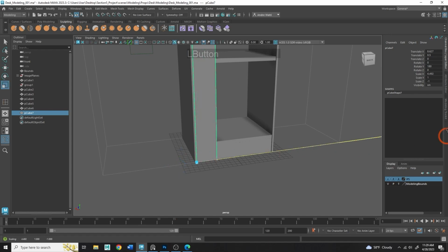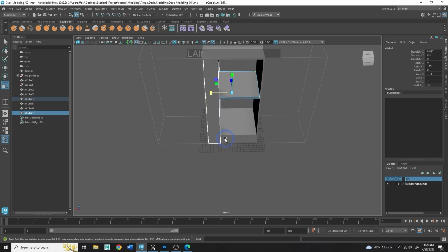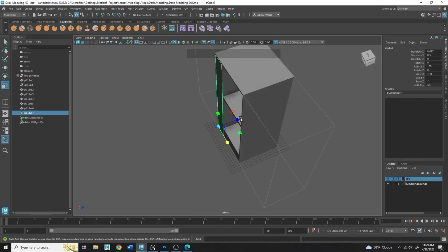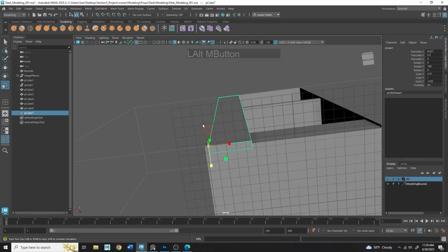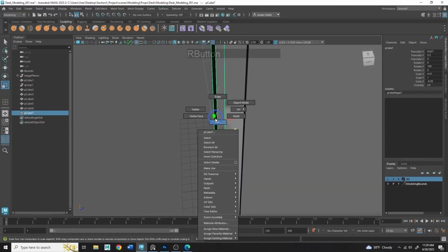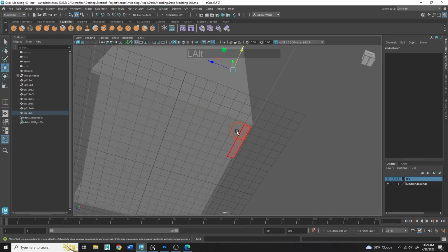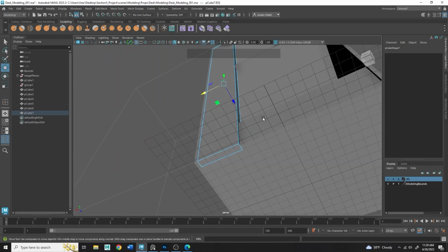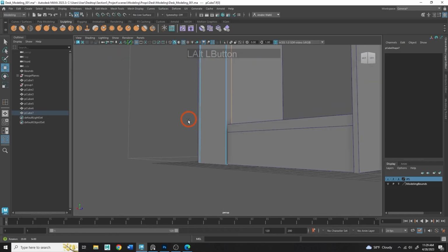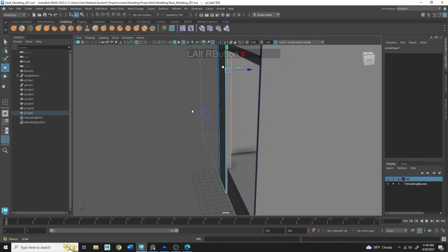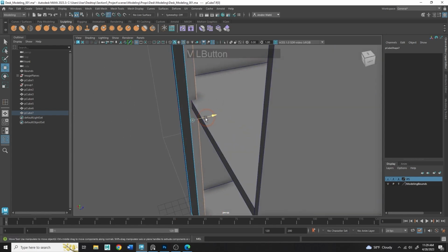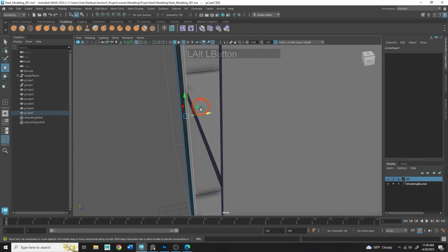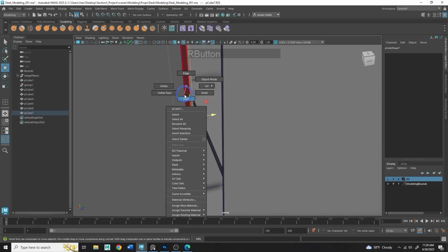From there, we can scale this across if we wanted to, or perhaps more appropriately scale it down to begin with, and start snapping these into the correct locations. What do I mean by that? Well, this face can snap to these vertices to have a tighter look. So this bottom vertice here, if I turn on wire on shaded, we can get a better feel for it. So just these outside ones, and this is going to be very thin, but if I find something like this shelf, just hold down V and try and find a vertice to snap to. Over there is giving me a vertice. You can also just eyeball it for this. It doesn't have to be that precise.